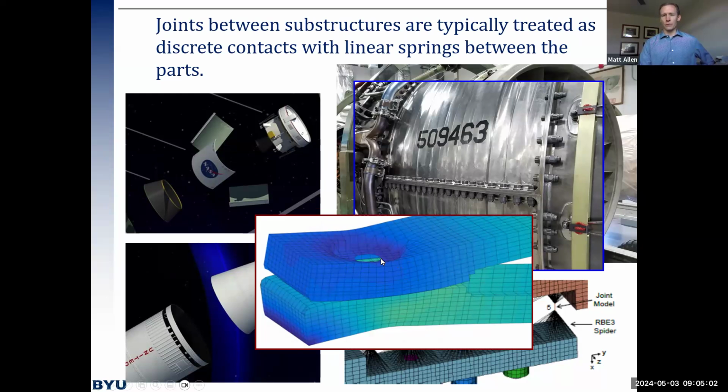This is what you'd get if you bolted two rubber erasers together, but the same thing happens with metals, just with smaller displacements. So you get areas of high pressure and areas of low pressure where the slip can easily happen. And so even for relatively small vibrations, you can get slip and nonlinearity and energy dissipation.